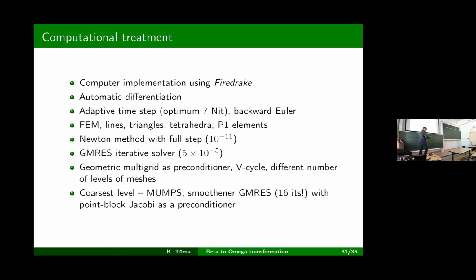And as a solver, in 1D this is cheap, so we are just using a direct solver, and we are still playing with this. For these problems, we now switch for some time to AMG, algebraic multigrid. And extremely experimentally, in an engineering way, we tune some of the parameters so that it works as well as possible.